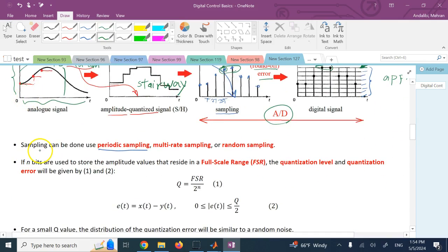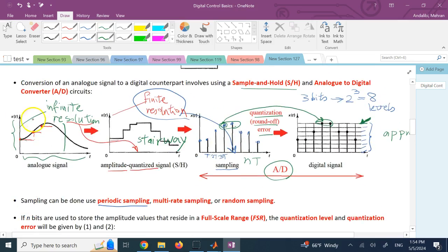So this sampling, the one that I showed you, is done at basically regular intervals, which we call sampling time. So in general, it's like n times T, correct? So here you see your signal is x of t. In here, it's not really x of t anymore. In here it is actually x of n times capital T. And here they are quantized to 8 levels.